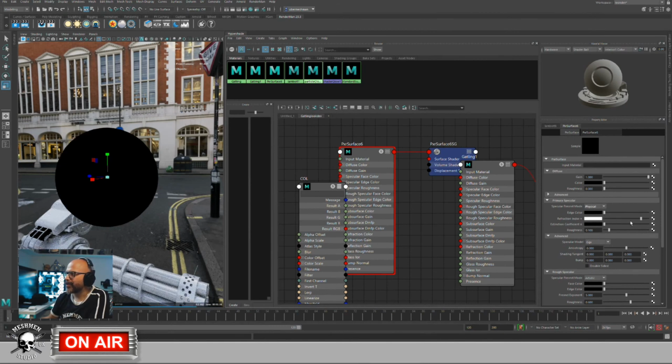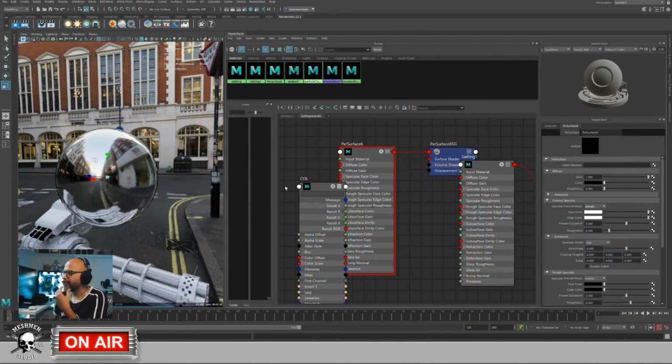Oops, what did I do there? I took it to physical. Going between the different roughnesses, we can see the difference between Beckmann and GGX is minimal at low roughness, but it's more visible around 0.2 or so in roughness. I think the GGX is superior in the look rather than Beckmann. Beckmann is more made for pure metallic, mirror-like surfaces. You can see GGX blooms a bit more there, and that's something I like.